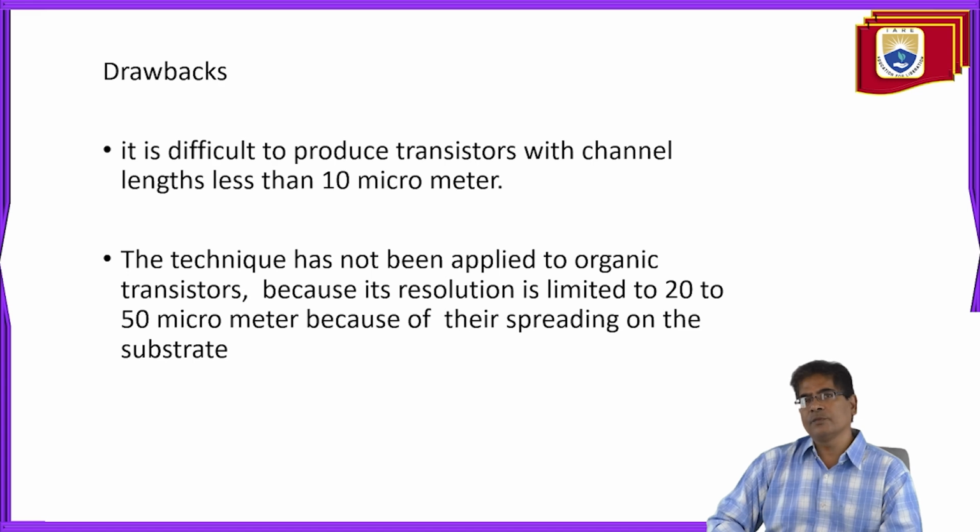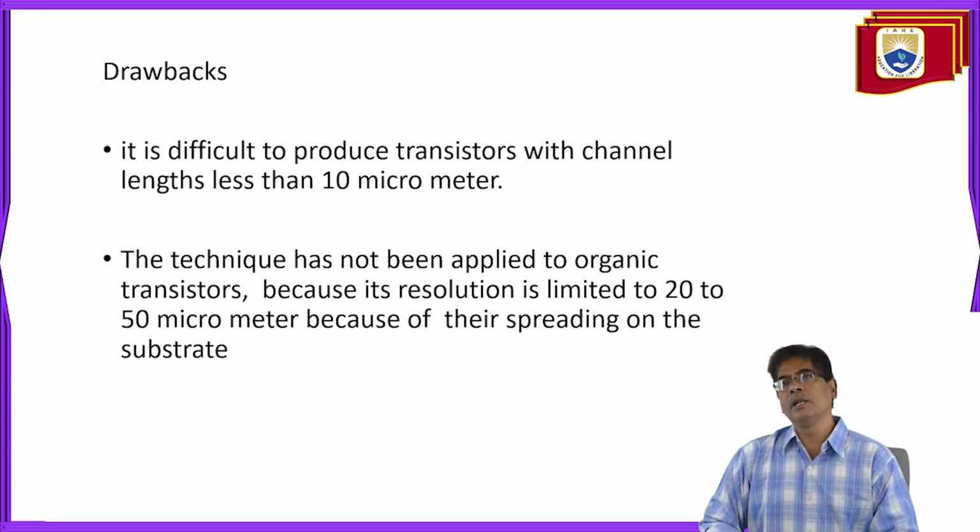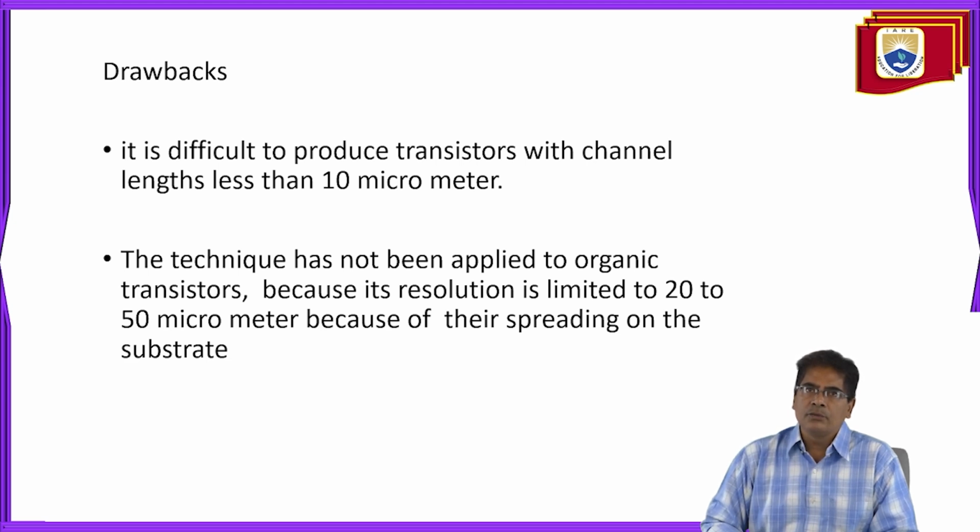And what are the drawbacks of this technology? It is difficult to produce transistors with channel length less than 10 micrometers. This technique has not been applied to organic transistors because its resolution is limited to 20 to 50 micrometers because of the spreading on the substrate.